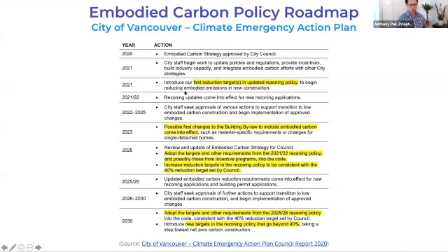And the general strategy is to have the rezoning requirement lead the building code by about 5 years. So do the ambitious stuff on the rezoning side. So for example, we're going to go at least 10% on the rezoning this year. And then in 2025, they'll update the rezoning requirement, probably bring it more in line with the 40% target. But also at that point, they'll have the building code adopt the previous 2021 rezoning requirement. So if it's 10 or 15% this round, in 2025, that'll kind of filter through to the rest of the code. And then by 2030, they'll bring it all in line and the rezoning will be pushed up even above 40%. So that's a high level overview of where the plan's going.